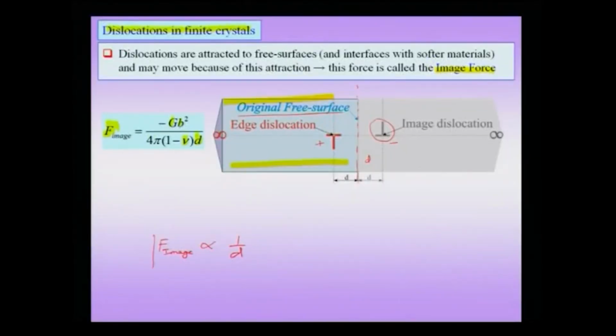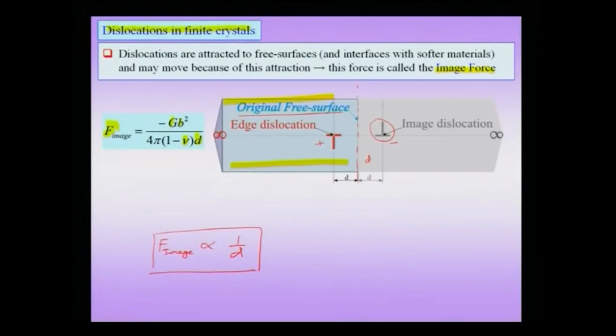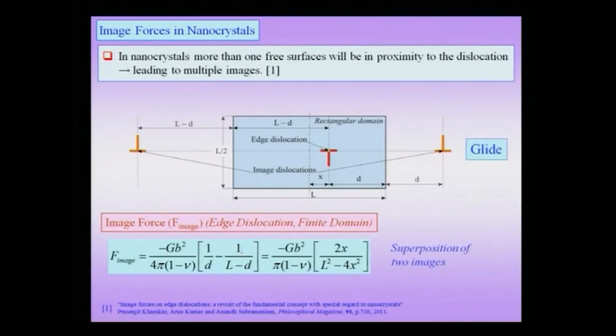Nevertheless, we now concentrate on the force, and notice that when a dislocation is positioned in a semi infinite crystal, it feels a force towards the free surface, which is called an image force. The value of the image force gets more and more intense, because it goes asymptotically with d as the dislocation is positioned closer to the free surface.